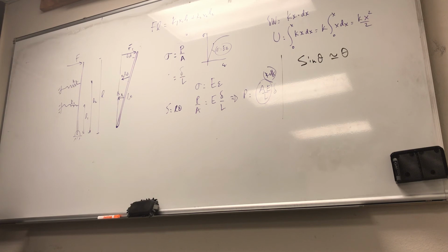So what they do, if you have a multi-story building, let's say I'm just taking this 1, 2, 3, 4, 5, 6, whatever. What they do is they take half of this wall and lump it with this up thing. And then they take half of this wall here plus half of the one at the bottom, right? And lump it into this. See what I'm saying? And then same thing in here, right? So that they can account for all the masses.